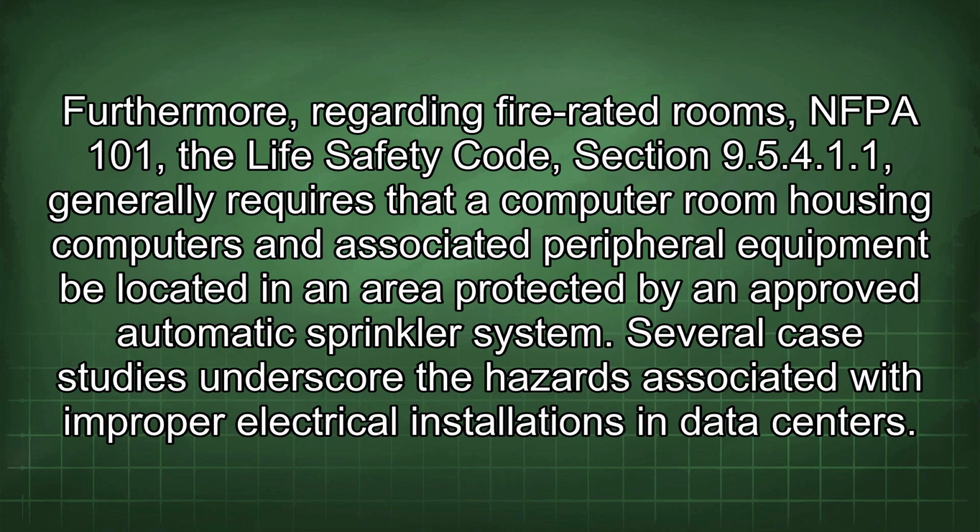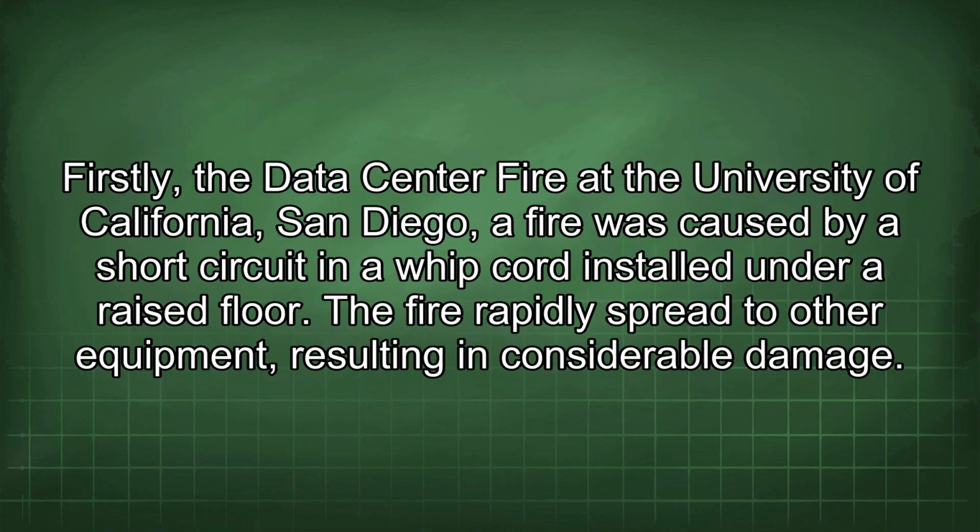Several case studies underscore the hazards associated with improper electrical installations in data centers. Firstly, the data center fire at the University of California, San Diego. A fire was caused by a short circuit in a whipcord installed under a raised floor. The fire rapidly spread to other equipment, resulting in considerable damage.